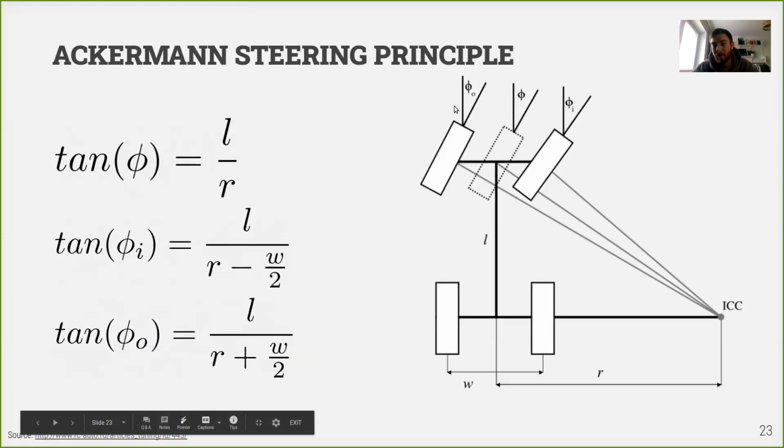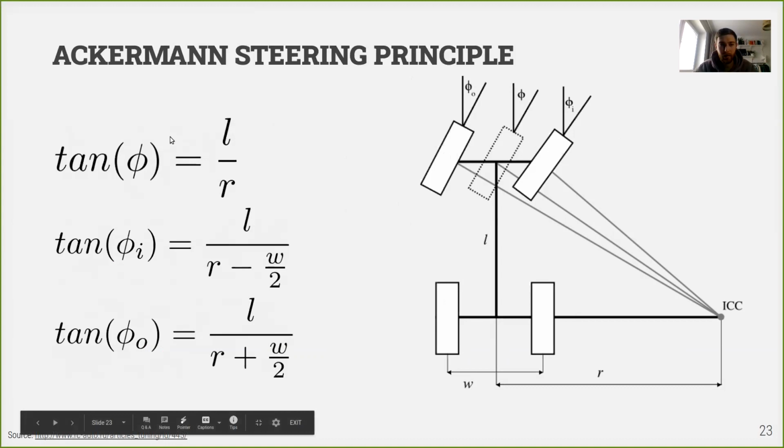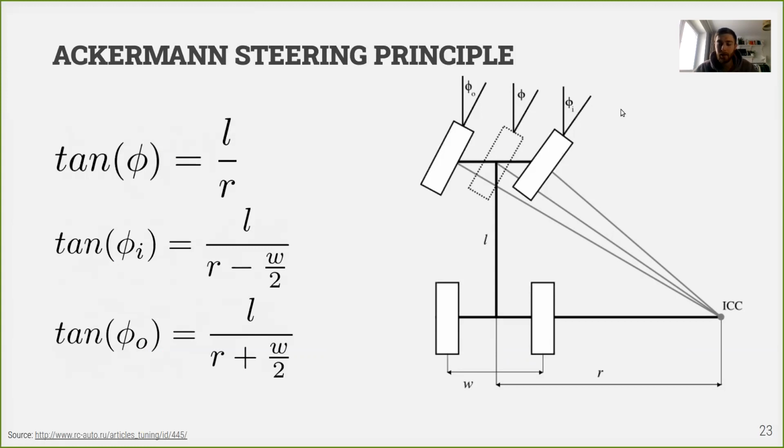And actually, when we're talking about motion models, when we are modeling robots kinematically, we usually substitute these two complex wheels with different radius of rotation with a single wheel, whose rotation radius is like the average of those two. And this quite simplifies the mathematics in our kinematics models.